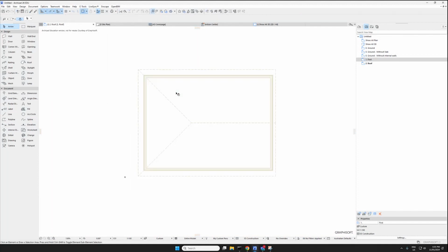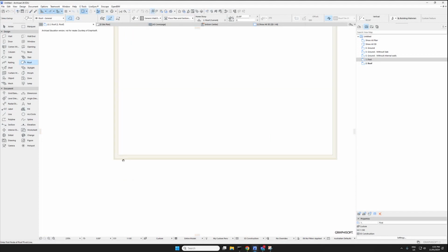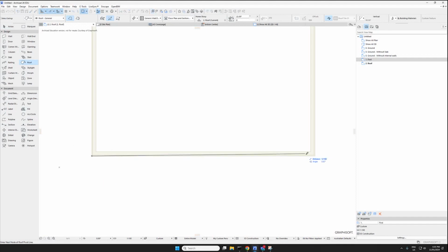Okay, so I'll delete this roof and start with another roof. So click on the roof and then go single plane geometry and click on here. And then this is a rectangular method, or whether we want it to be a complex roof. So we'll keep it rectangular for now. And we're going to go around small. So where is the pitching point? That's where I'm defining it to. So I'm defining this point or this line to be the pitching point. And then the eye should be towards where it's sloping down to.